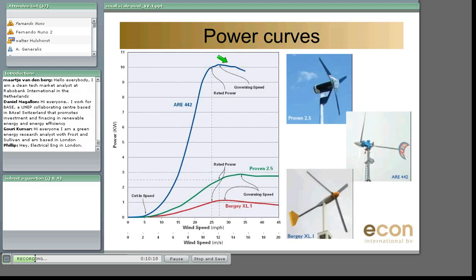You will also notice that at a certain point, when the wind speed keeps getting larger, this wind turbine is not going to give you any output. So basically for this situation we have a cut-out wind speed of about, let's say, 15 meters per second, or about 35 miles per hour.